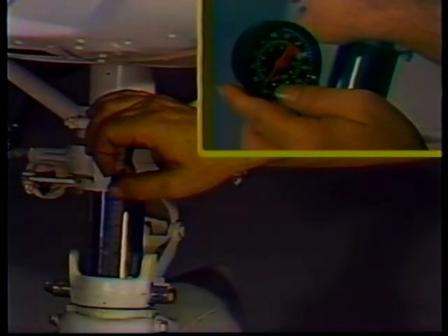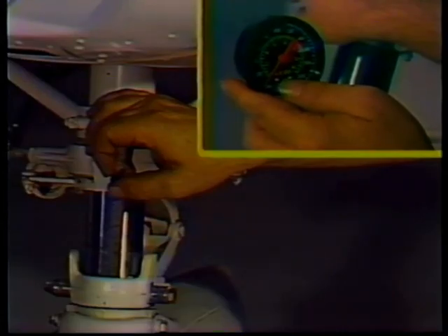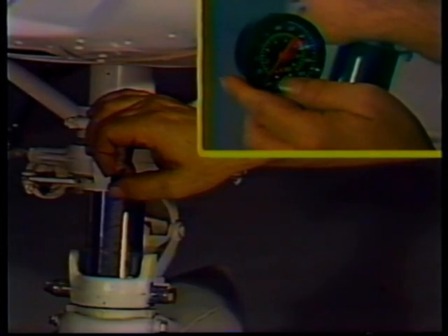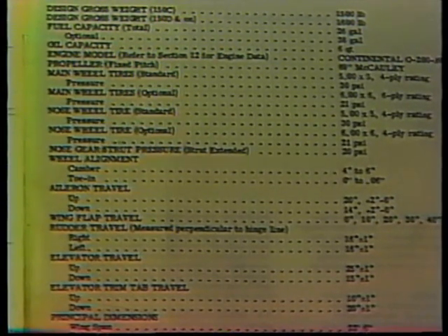On some shock struts, the correct amount of inflation is determined by using a high-pressure air gauge, while others require that the extension between 2 points on the strut be carefully measured. The proper procedure for measuring inflation can usually be found on an instruction placard affixed to the strut, as well as in the service information.